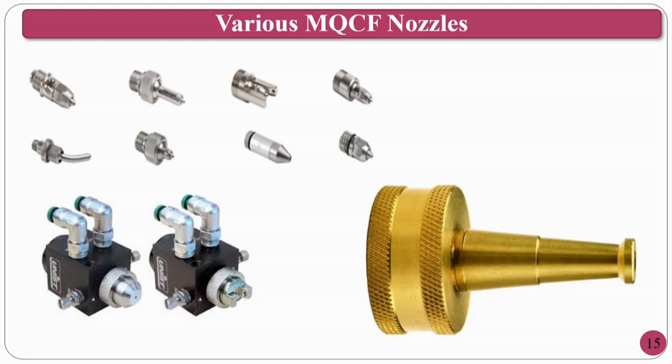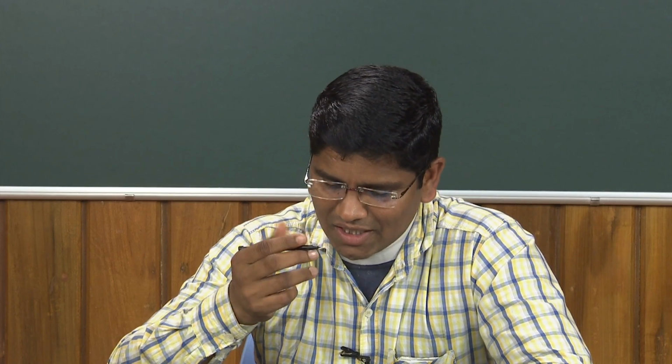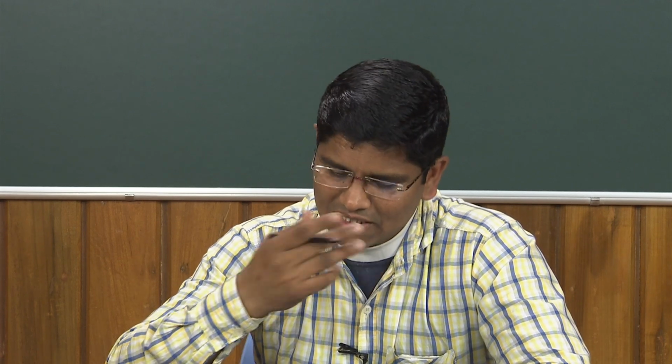Okay. These are the other varieties of nozzles which you have seen already. I want to emphasize two things: one is internal mixing as well as external mixing. If the cutting fluid and air both are mixing outside the nozzle, that is called external mixing. If both are mixing internally, that means within the nozzle system there is a mixing chamber, and if it is mixing there and the mist comes outside, that is called internal mixing. If it is mixing outside the nozzle, it is external mixing. If it is mixing within or before the nozzle exit, that is called internal mixing.